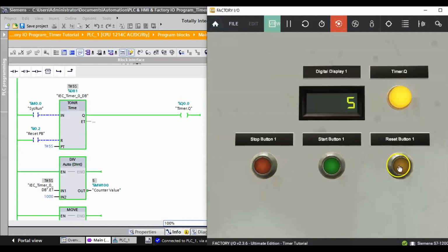Beautiful. All right, guys, so we've gone through all the different timers with this simple project here. Next week, we're going to bring everything together. So we're going to go back to doing our conveyor project, and we're going to make use of this timer. Like, we're going to have some flashing lights. So we want when we hit the start, we don't want the conveyor to turn on for a couple seconds until a flashing light has gone off to tell the operator that the conveyor is going to turn on.